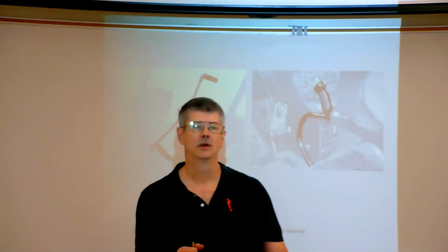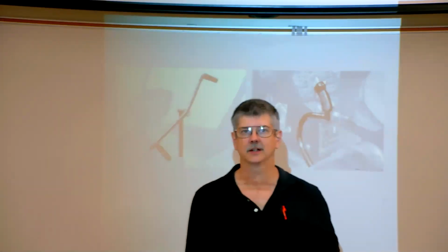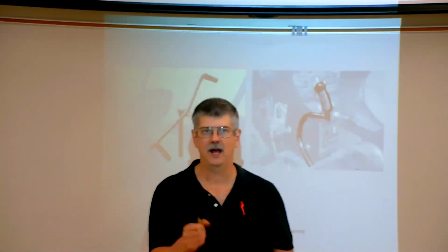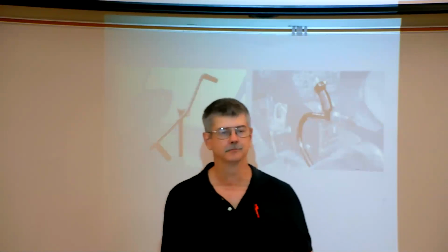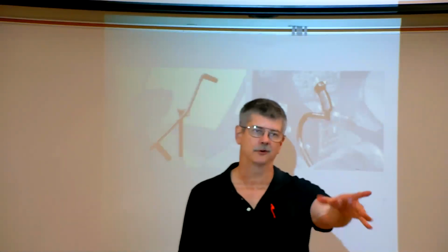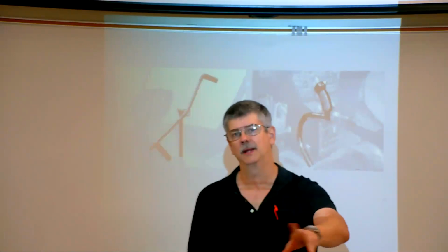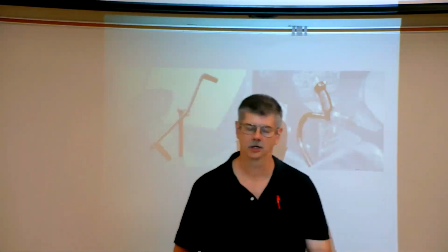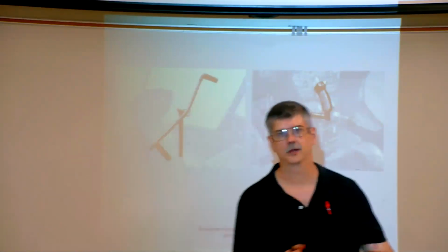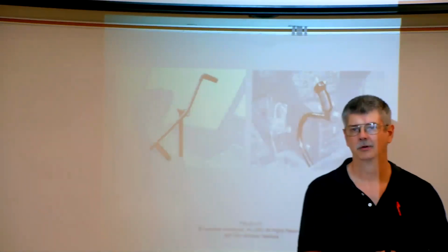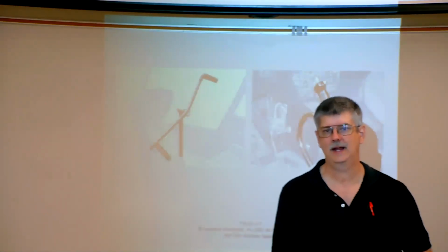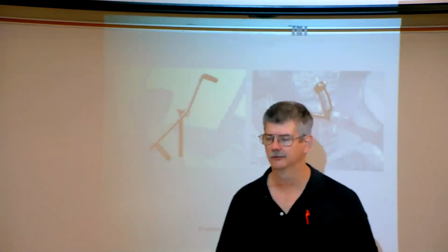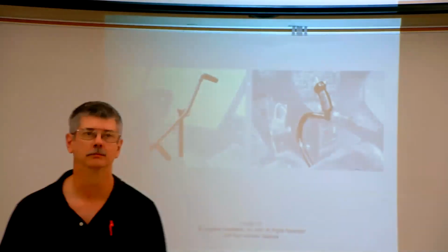So the pilot can usually set the collective and then fly just with the cyclic, and then they have a free left hand to operate the controls that are in the center. Whereas if they're in the left seat, flying with the right hand, it's really difficult for them to release that hand to activate those controls.